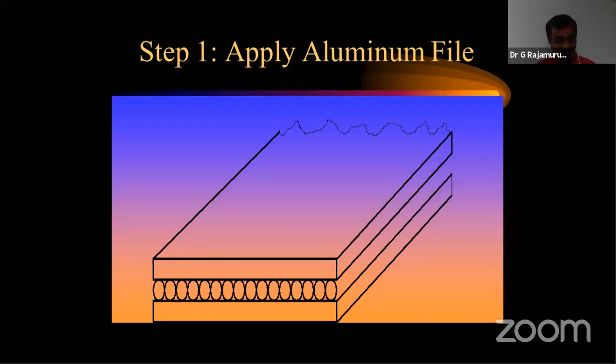That we call delamination. So in order to avoid this delamination, while adding this aluminum foil, what should I do? You should make some holes at different distances on your aluminum foils. Okay, that is called perforating.